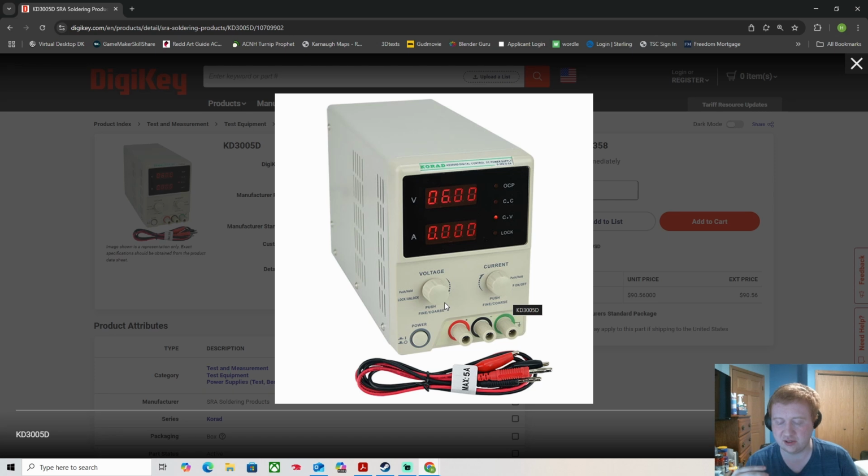But as soon as your resistance drops too low and the current would increase beyond 1 amp, the machine kicks in a safeguard and forces the output to regulate at 1 amp regardless of what's connected, so that it doesn't burn out the supply, and so that the load, which couldn't handle the wattage either, doesn't burn up.